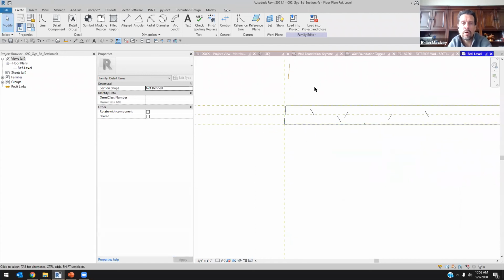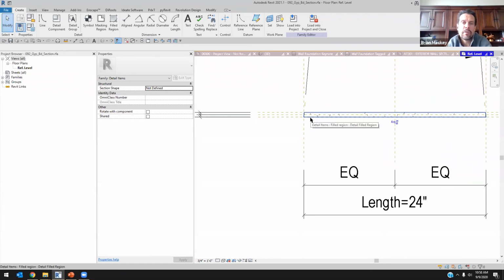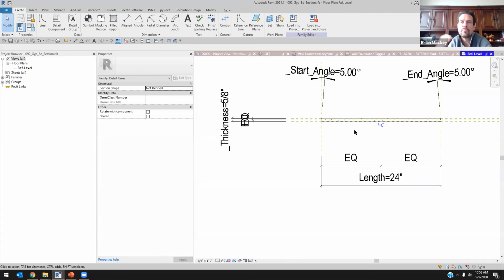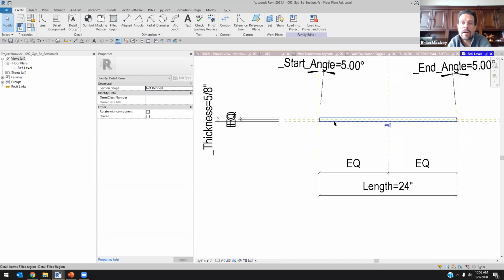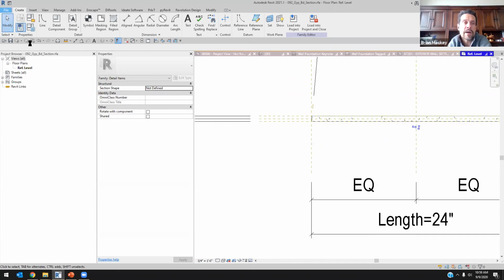Now, one other thing that's really nice is, great, let's say I've done the gypsum wall board, and yeah, I have the gypsum wall board one here created. Now you need one for concrete. What's really great about Revit, and what didn't take me so much time to do a lot of this, is once you get one set up and tested, you made sure you've put it in a project, you've played with the start angle, the end angle, you've added comments, type comments, etc. Once you've got that stuff all set up and done, what's great about it is it's simply then a save as, right? I go in, I go file, I do a save as on this,